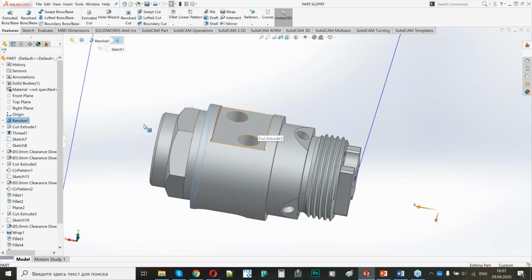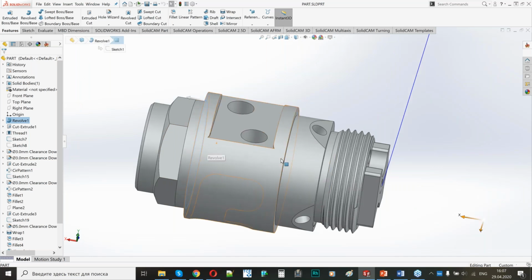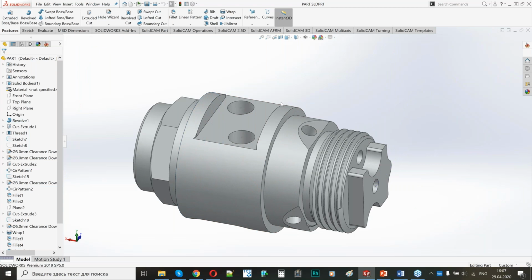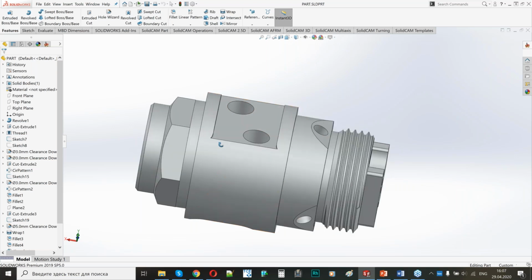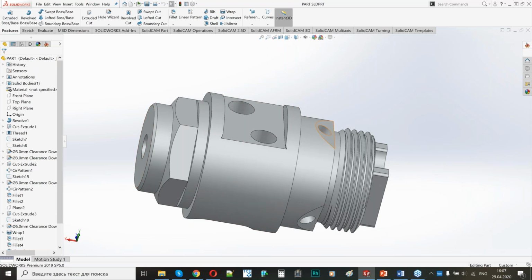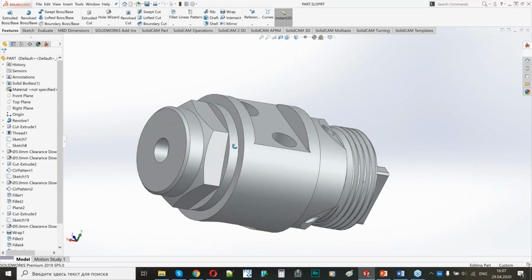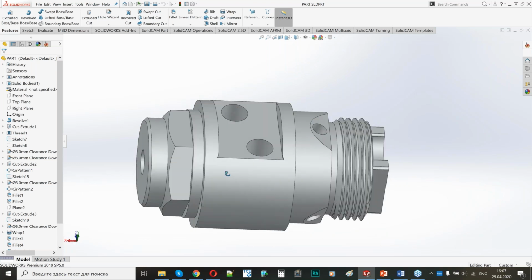During the cutting of the second piece, the part should not retract back completely to the collet. This is the condition which we should support on the Swiss type machines. So I should be careful with my Z1 retraction to the collet. And today I will show how we can program this inside SolidCAM. Then I'm gonna program the cutoff process, part transfer, and I will program all these elements on a back spindle.